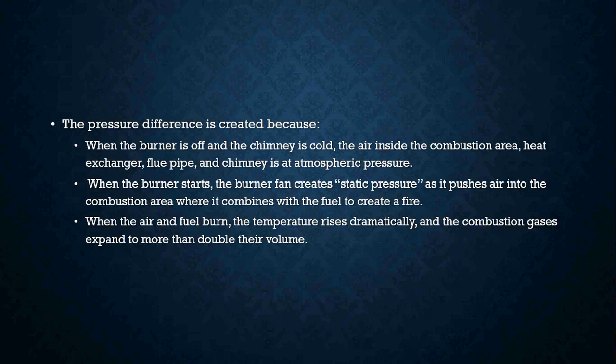The pressure difference is created because of a couple of different reasons. When the burner is off and the chimney is cold, the air inside the combustion area, heat exchanger, flue pipe, and chimney are all at atmospheric pressure, 14.7 psia. When the burner starts, the burner fan creates static pressure, and that pushes the air into the combustion area where it's combined with the fuel, therefore creating a fire.